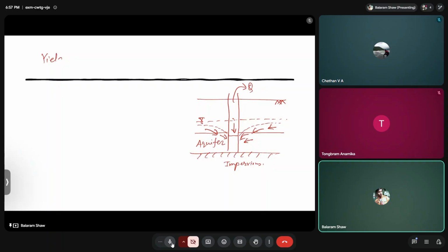Okay, fine. So here we discussed three terms. First one was drawdown, right? What was drawdown? Drawdown is the distance between the pumping water level and the static or rest water level. So if this is the rest water level, and here we have the new water level, this length we call head loss, right? Because of this head loss, the water table has moved, to the dashed line which you can see. This we call drawdown.